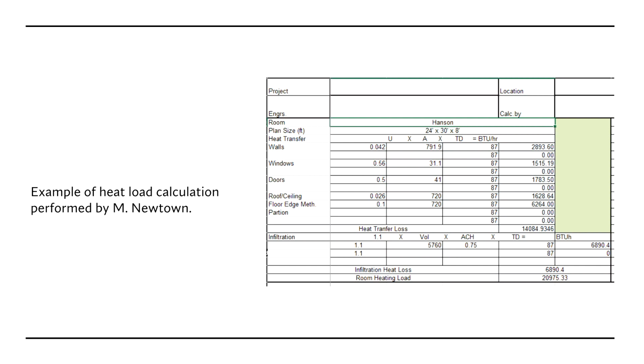Okay, so infiltration is a measure of unwanted air that's not through clean passageways. And there's a really great word used in building science: interstitial spaces. That is spaces that are between the walls. It is notorious when I do energy audits on houses that I can always find interstitial passages that bring air from the basement upstairs, air spaces that go from outside to inside, and then vice versa.